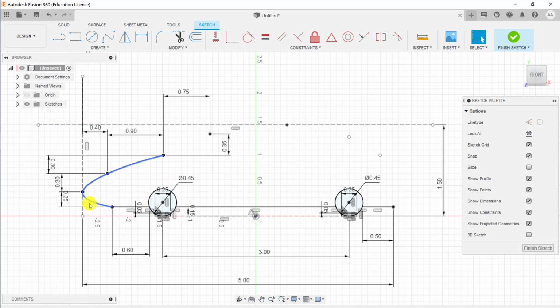Since our car is a little bit tipped forward here, like the dimensions, it's longer in the front, I'm going to move this point a little bit farther back along the x-axis. So let's dimension it relative to the origin this time. We're going to dimension it to 0.25 meters behind the x-axis. And since we want to keep our height at 1.5, let's just keep the point on the line. And that point should be fully defined right there. So that's perfect.